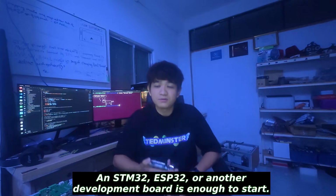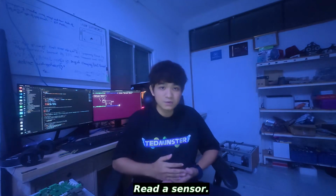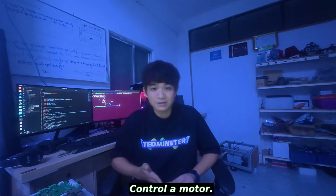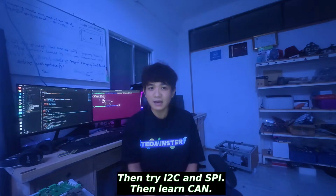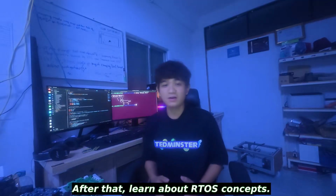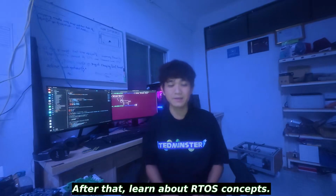Another development board is enough to start. Build small projects: read a sensor, control an LED, generate PWM, drive a motor, read an encoder, communicate with UART, and then try I2C and SPI. Then learn CAN. After that, learn real-time operating system concepts.